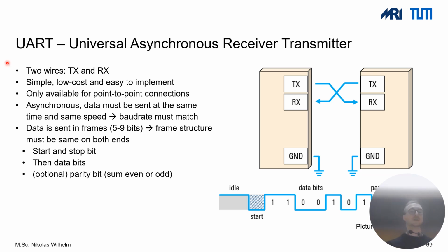And then a very simple system, the more or less classical one that is not used that much anymore nowadays, is UART, the Universal Asynchronous Receiver Transmitter. This is asynchronous, whereas all the other signals were synchronous. Before, we always had the system clock that determined when we want to send signals. Here we do not have this, but this comes with some additional requirements.